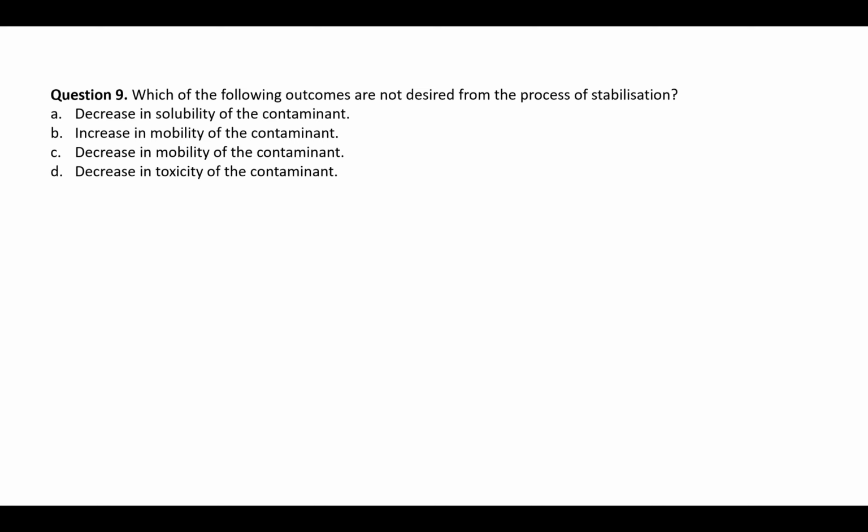So the outcome which is not desired for the process of stabilization is increase in mobility of the contaminant. So B is the correct answer. The first option, decrease in solubility of the contaminant: in solidification and stabilization, we want the solubility of the contaminant to decrease. Next, increase in mobility of the contaminant.